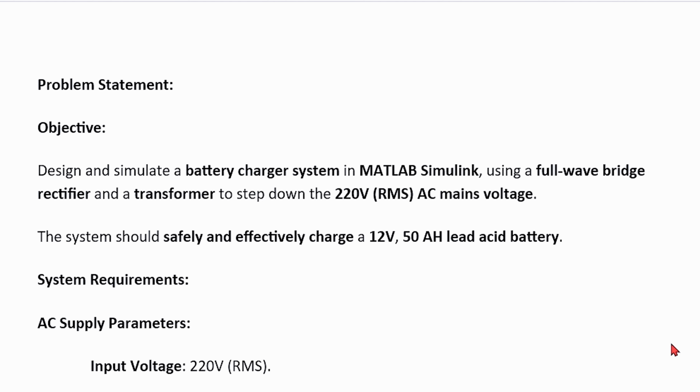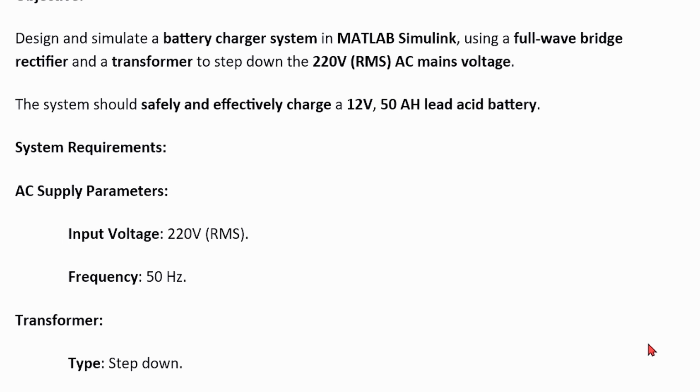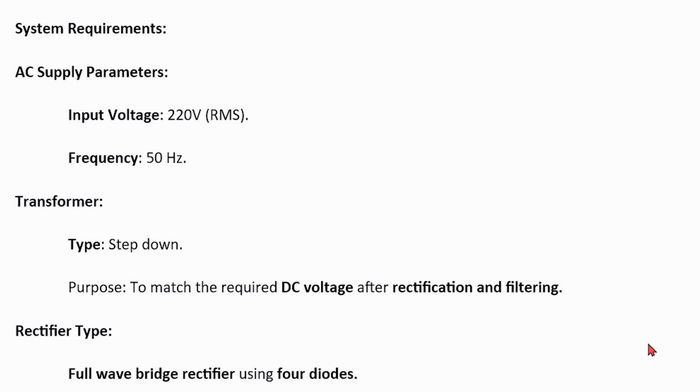Problem statement. Objective: Design and simulate a battery charger system in MATLAB Simulink, using a full-wave bridge rectifier and a transformer to step down the 220 volts RMS AC mains voltage. The system should safely and effectively charge a 12 volts, 50 ampere hours lead-acid battery.